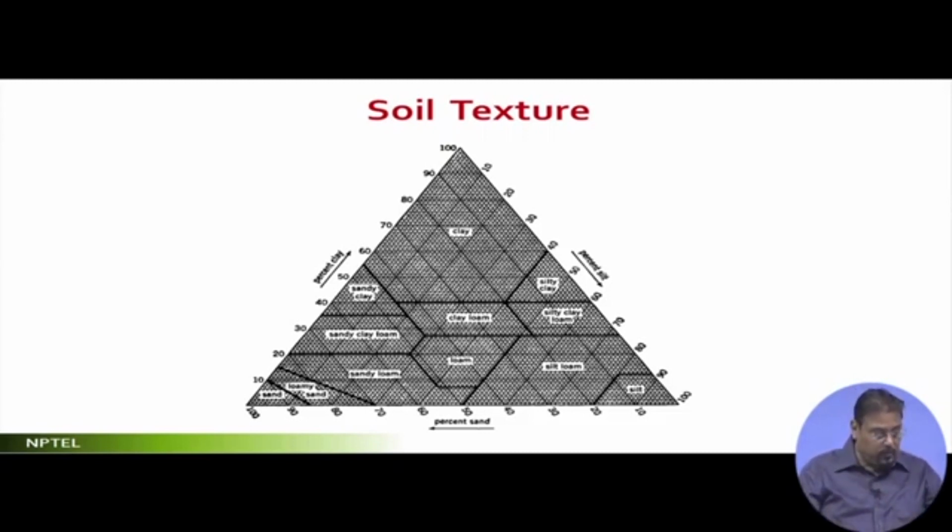Follow this particular chart, this is the region that has been considered to be loamy, and loamy is the best kind of soil, good for vegetation purposes and also for strength. The more you go to sand, unless it is bonded with a good quantum of other organic matter, it becomes almost a loose material.